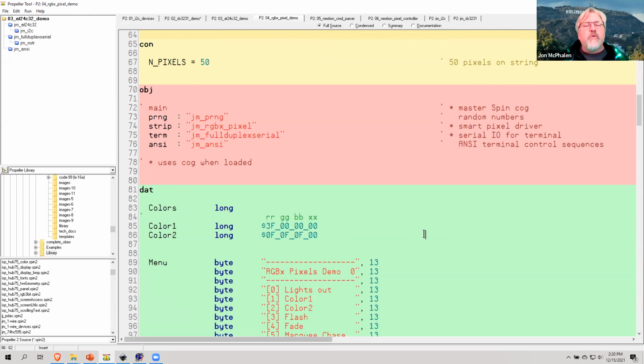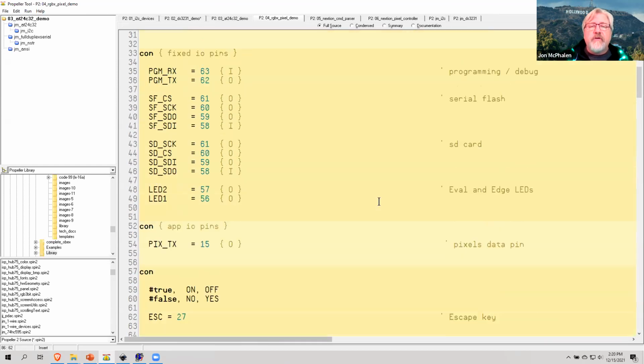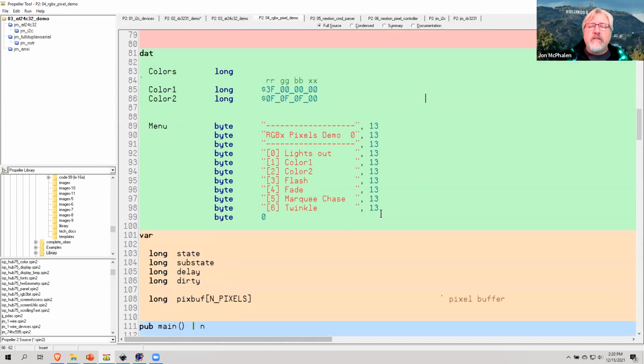Those generally have WS2812s. Now, some of you that participated last year were going to say, hey, way to recycle, JonnyMac. Well, you're right, I did. This is a lot of that same code, but heavy but. This code is written in a better way because it's state driven. There are no delays built into this program. Everything is run in a state machine, which is really a better way to go.